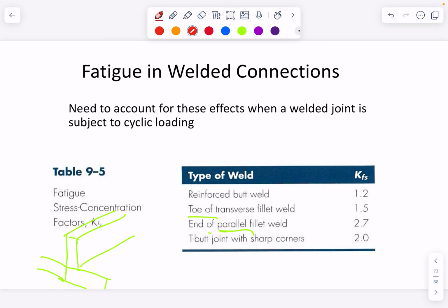If I pick up my welder and I strike an arc and I start welding along this way, well, when I very first start that arc, this material here is cold. By the time I get moving a little bit, I've got heat running away in all of those areas. So I'm getting that metal ready to accept the weld.